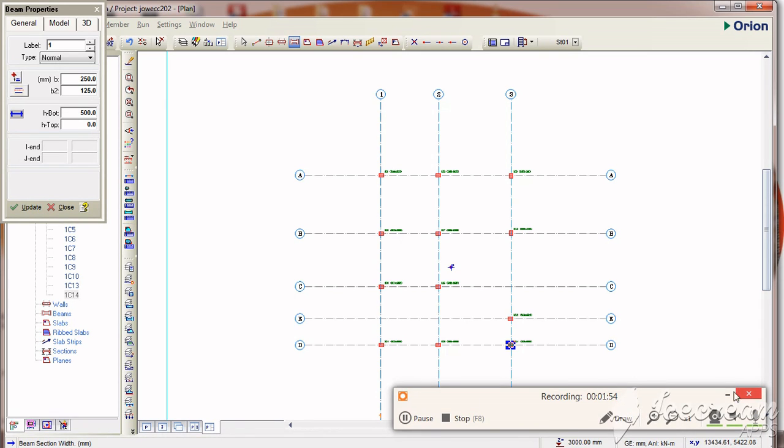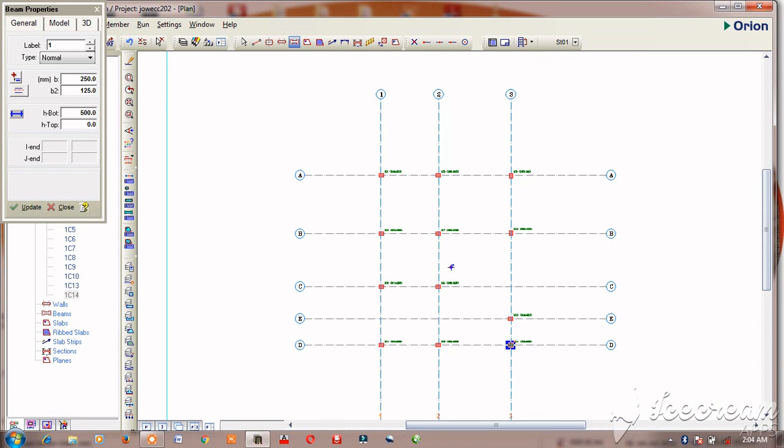Right. The next thing is a beam. So how do I insert my beam? I have clicked it here, beam, and this is the size of my beam, that is 225. This is the eccentric, that is the center of my beam, that is 112.5.